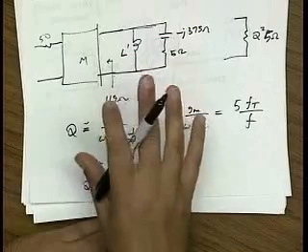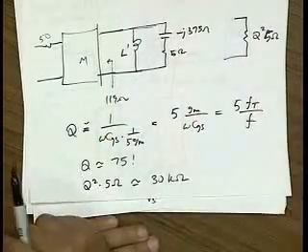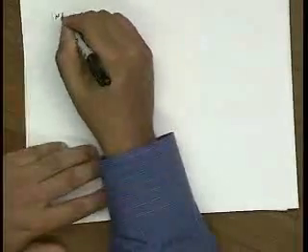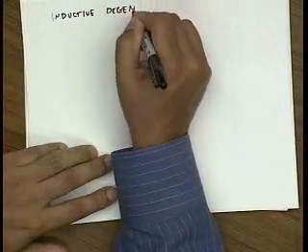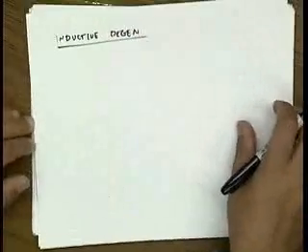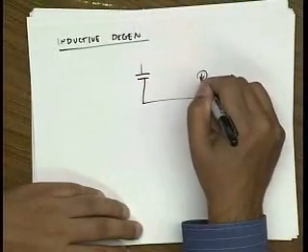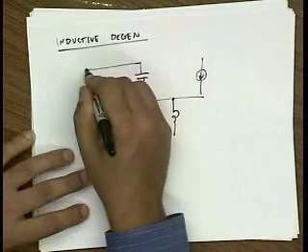But at the end of the day, this is not what you have anyway. When you package it, you get these extra inductors. So the most popular way to do it is to use inductive degeneration. Okay. And the idea behind inductive degeneration is, let me just calculate.